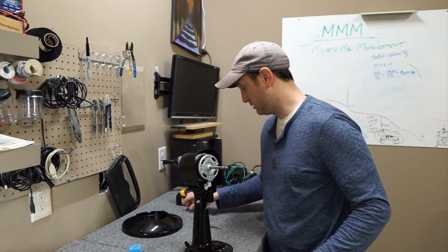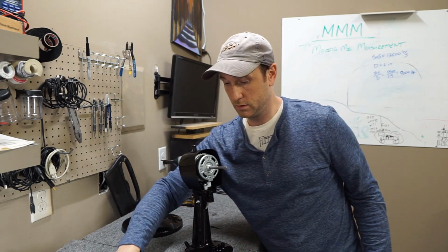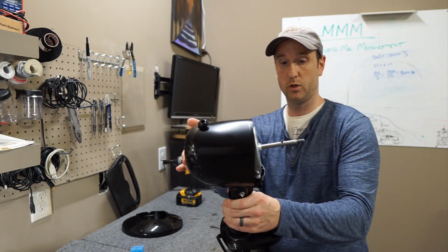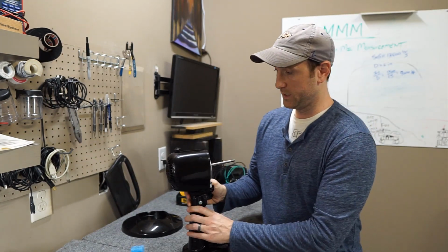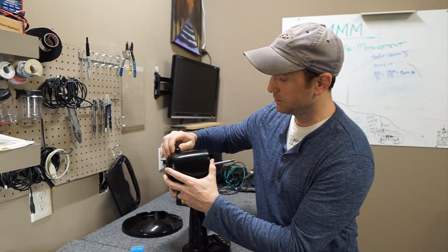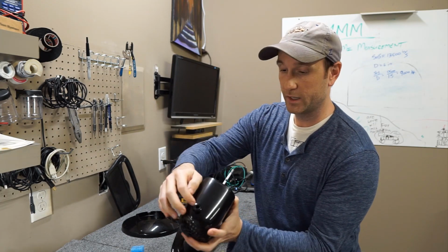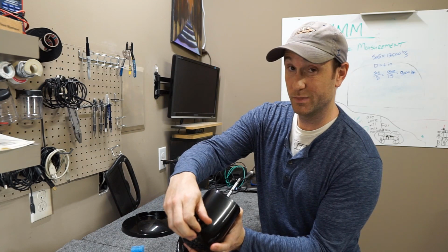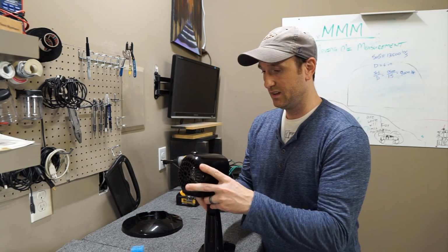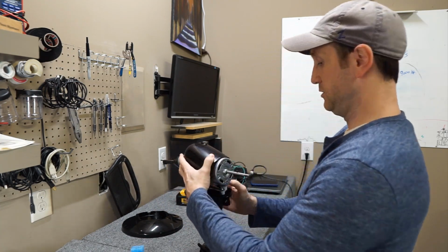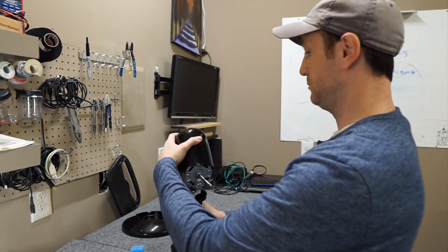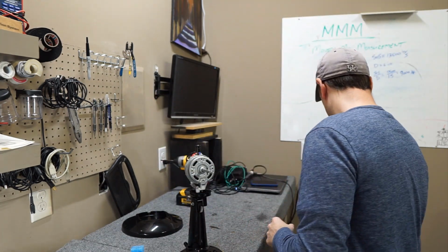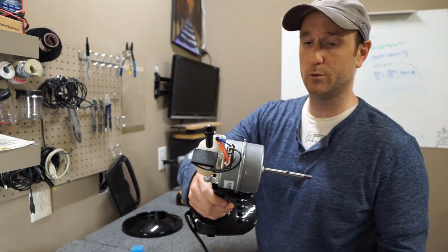I'll throw that over here. Hang on to the screws because you'll need at least 2 of those. Then you're left with this little wiggle wobble thing. In order to take it off, the main concern here is making sure that you slip the hole up over the piece that makes this thing oscillate. You'll have to fiddle around with it, but if you just push it from the bottom, tilt it up, it'll slide right over, no big deal. And I'll throw it down here too. You've got the inner workings of the motor.